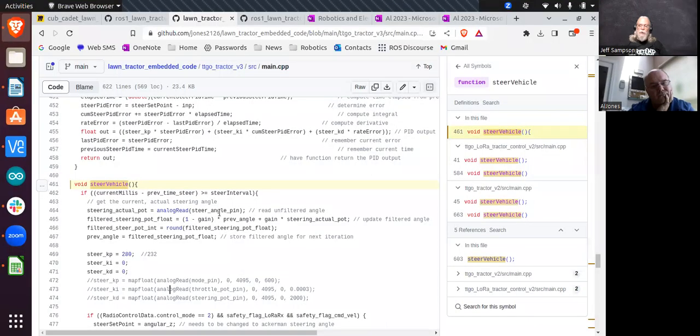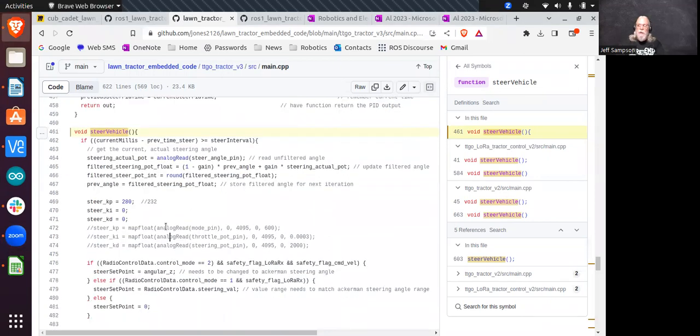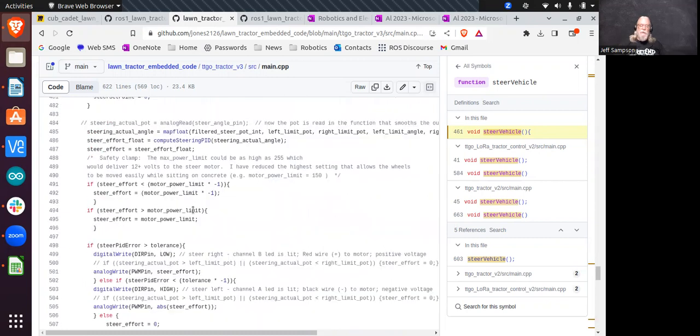So basically, in your code, each time you read the requested angle from ROS or the joystick, make a new variable called target angle, and you just track that. That's going to track the requested stuff coming in. Then each time you either add or subtract a value until they're equal, and if you're greater than that, just clip it to whatever the incoming value is. So all you're doing is slowing it down so it can't jump the full distance at one time.